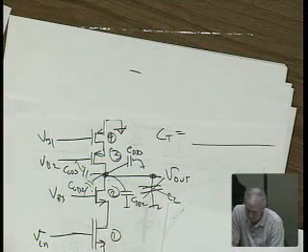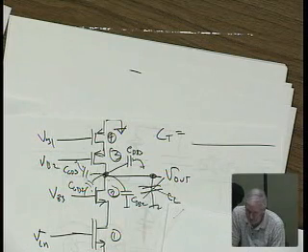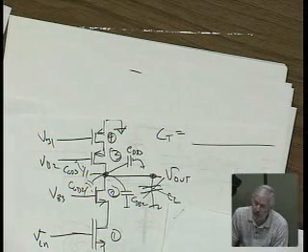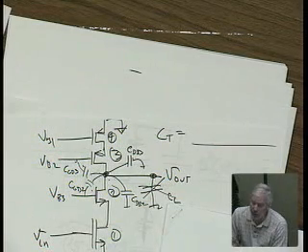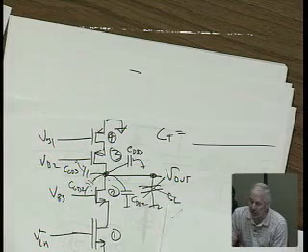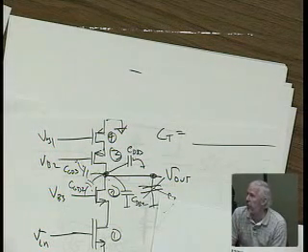Because it's a huge capacitor, we assume that it basically zeroes out the gain. When can you make that approximation? Well, it's at some frequency. At DC, the gain's still full gain, right? It's only when we're trying to calculate the pole location that we make this approximation.